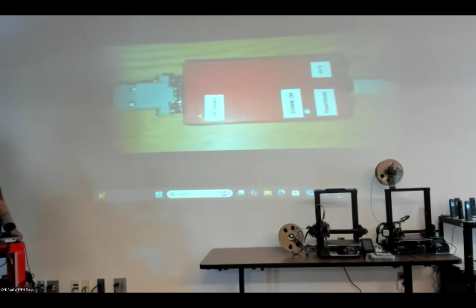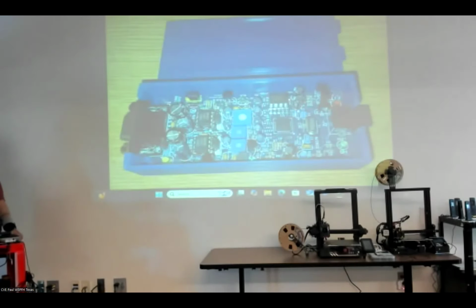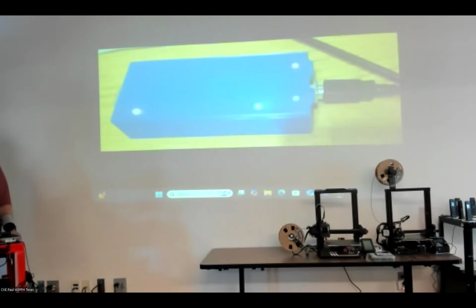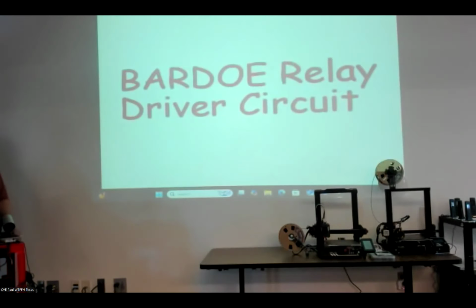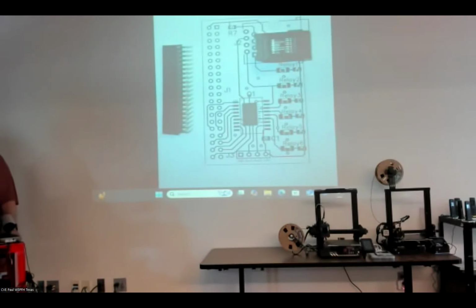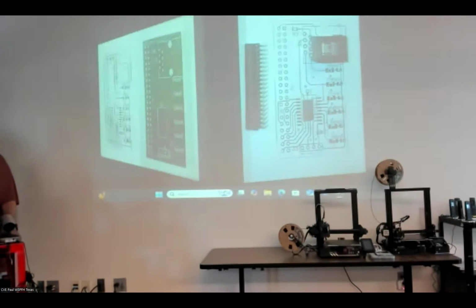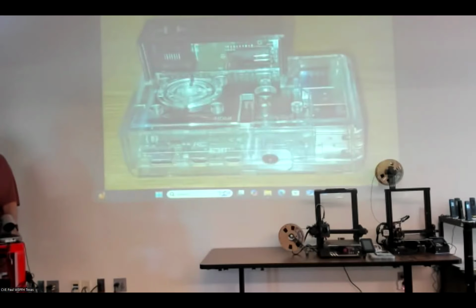It's hard to explain, but it's basically like somebody tied an overhand knot in the spool. And then of course it jams at the machine, it stalls the print, you end up with bad adhesion layers and everything else. And a lot of times when that happens, especially with PLA, it'll just snap. And if you don't have something like a filament runout sensor to tell you that the filament's no longer there, you could scrap a print real quickly.